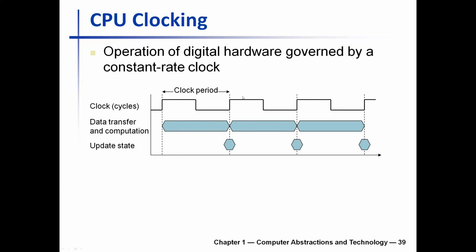We use such a signal to synchronize the operations of our logic hardware. At the rising edge, your circuits are designed to do certain things, and at the falling edges, your circuits are designed to do certain things. These things might happen periodically, or in alternating ways, but synchronized to these edges in the clock.